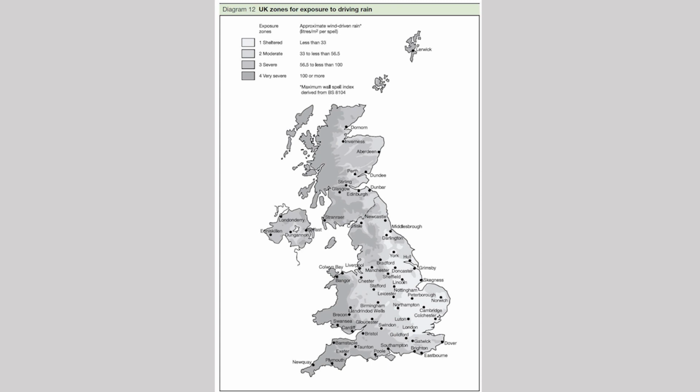Certain insulation types in a cavity wall, again, are not necessarily suitable for having that. So if you end up having a full fill cavity, then that might be acceptable with a particular type of insulation, but only in certain exposure categories. So if you were in a coastal area or one of these areas that's more subject to this wind-driven rain, those areas would not be acceptable for that particular type.